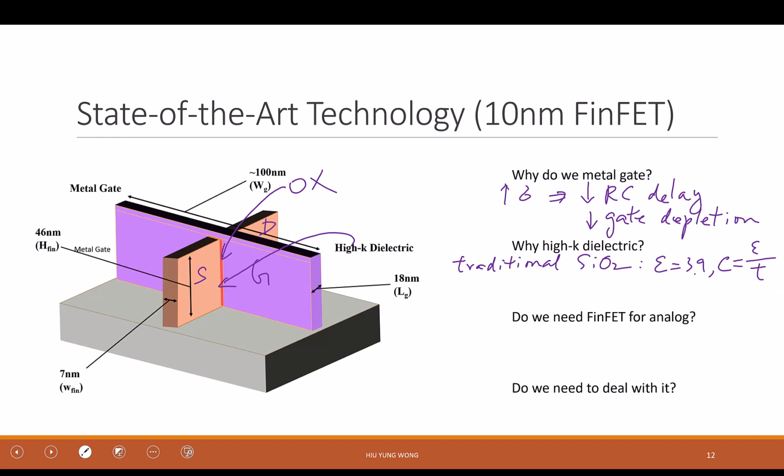So what can we do to increase the capacitance? Increase the epsilon, the permittivity, right? So for example, we can use hafnium dioxide, which is very commonly used, and its derivatives are used very often. It has a wide range, but maybe we can say about 30, okay?